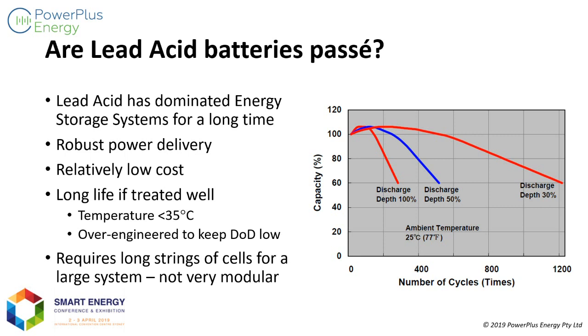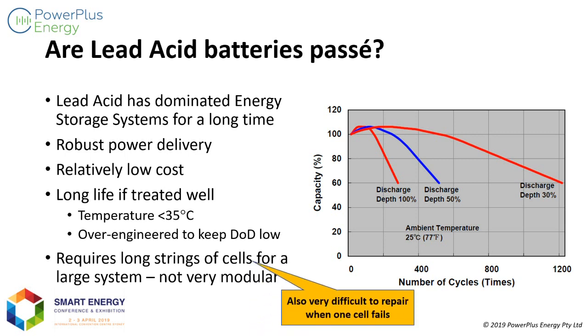I had a friend who's currently down in Mundrabilla Roadhouse trying to solve a problem with a large lead-acid system that was installed down there. He's got a bunch of cells that have failed because of temperature variations across the string. You can't just repair a couple of batteries in the middle of a lead-acid string, and that's where the beauty of lithium comes in. Now, as you probably know, lithium batteries have been around for a while.